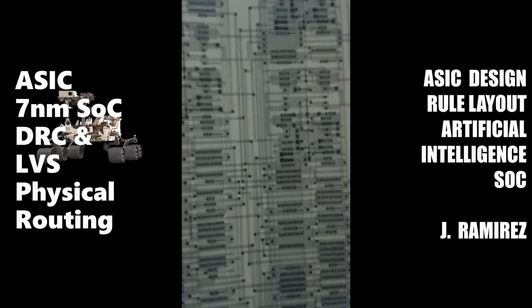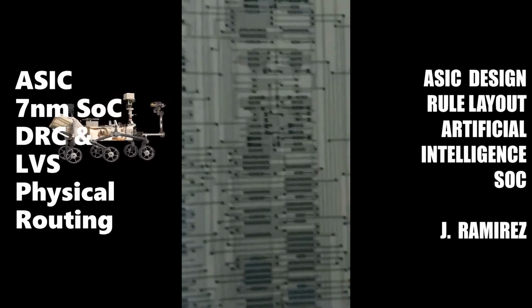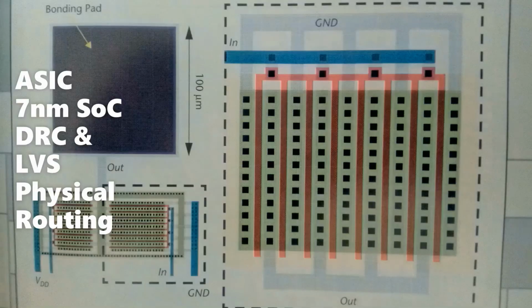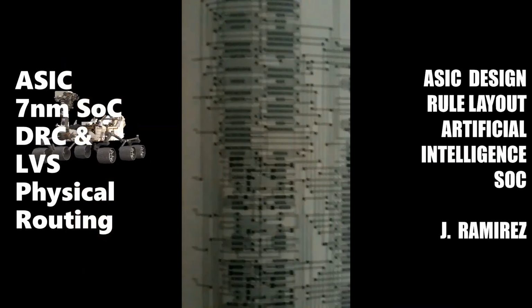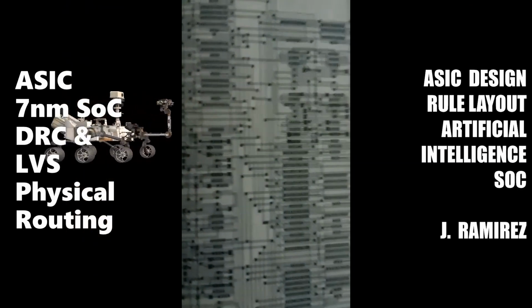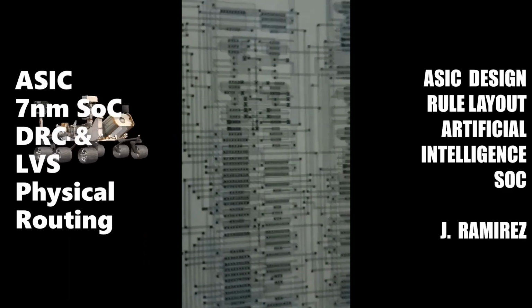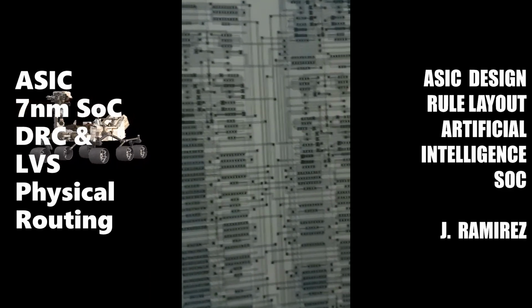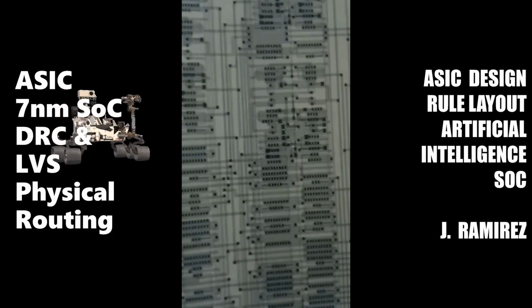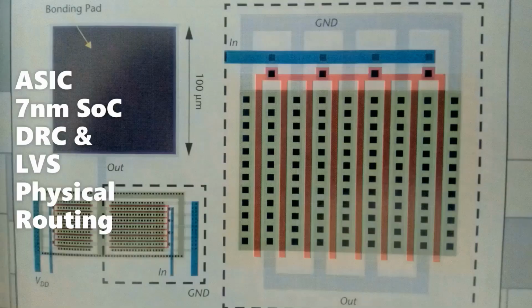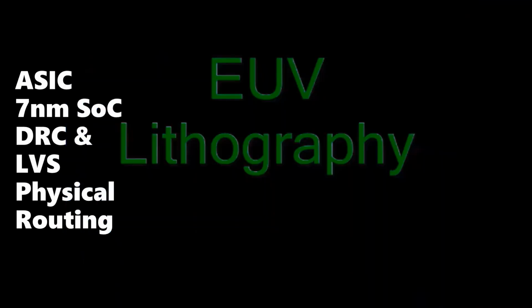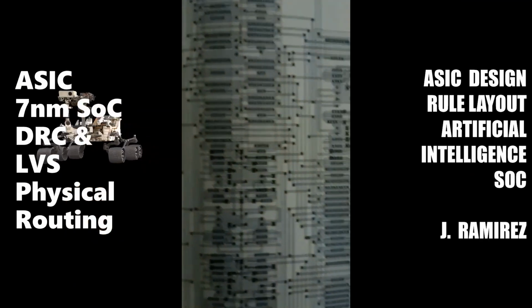The completion of routing finishes the ASIC physical design process. Global routing plans the wiring by finding the channels to be used for each path. The algorithms to find the shortest path are very similar. There are differences between global routing for different types of ASICs.